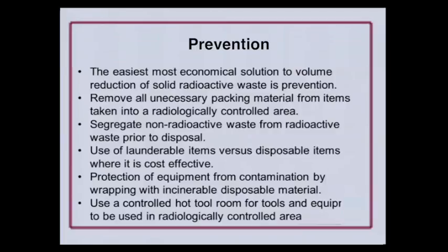Here's an item. Most plants use this, and I think SRS uses it. That you have what is called a hot tool. These are commonly used tools and equipment that have become contaminated that you keep in a controlled area for reuse, rather than taking new stuff in, getting it contaminated, and then once it's contaminated, thinking, well, it's trash, so we'll throw it away.